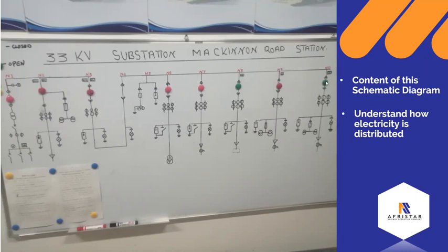And also, if N10 was off, we will just turn it on. We will first come and turn N9 off, and then we will turn N10 on, and the power will flow to this bus bar, and our substation will have power. So our substation, because we have this panel to help us separate the section of power, so that power can't meet.